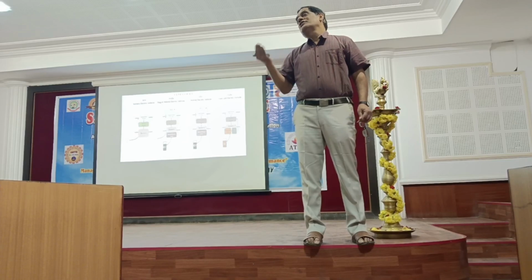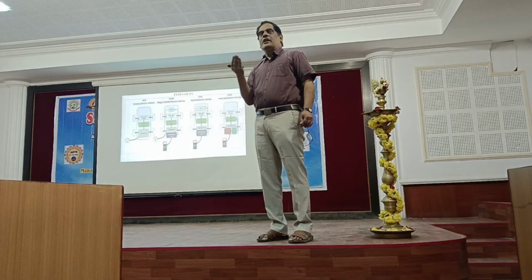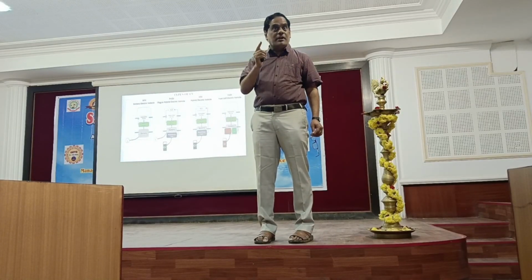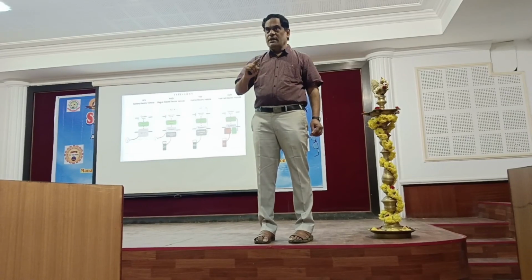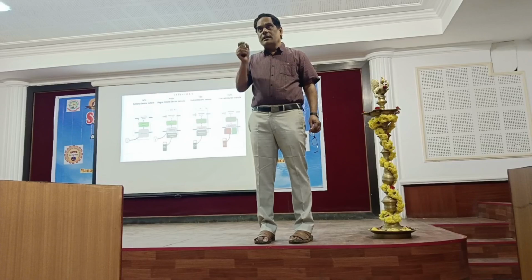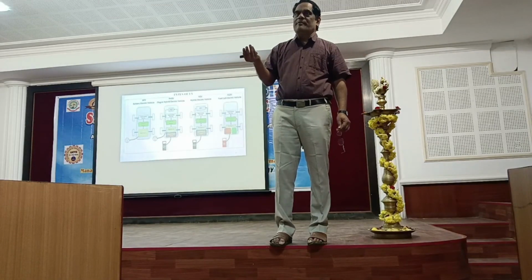Not being connected to the external load, what is the EMF each cell can actually produce? That we call the open circuit potential. This OCV value is very much required when the battery is being used continuously over a longer period of time. Each time you want to know at what rate cells are undergoing degradation, a simple measurement using a multimeter tells you what voltage it gives.